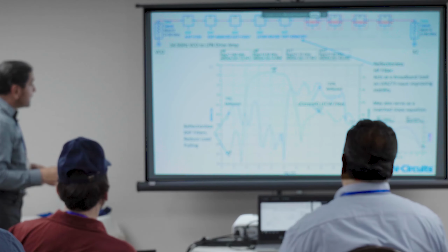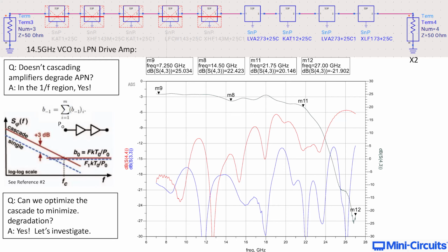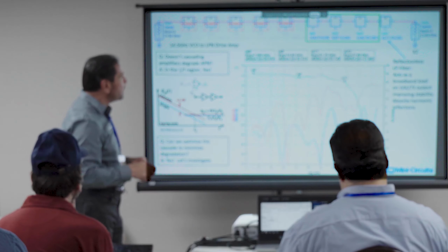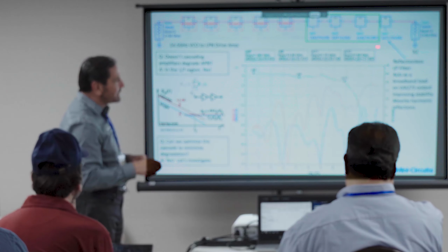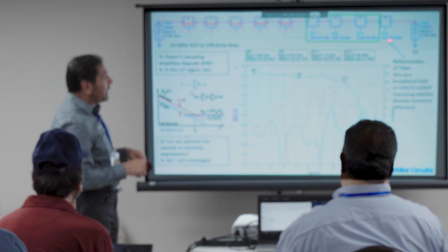Then we're going to go into this amplifier cascade ad nauseam later, as you'll see. And again, the pad in between, I think, is a basic building block. You should think about this as not just cascading amplifiers, but cascading so that you can control the input power into each amplifier. So there's another guy here. I just love to use these things, right? I don't get extra money if I use them.